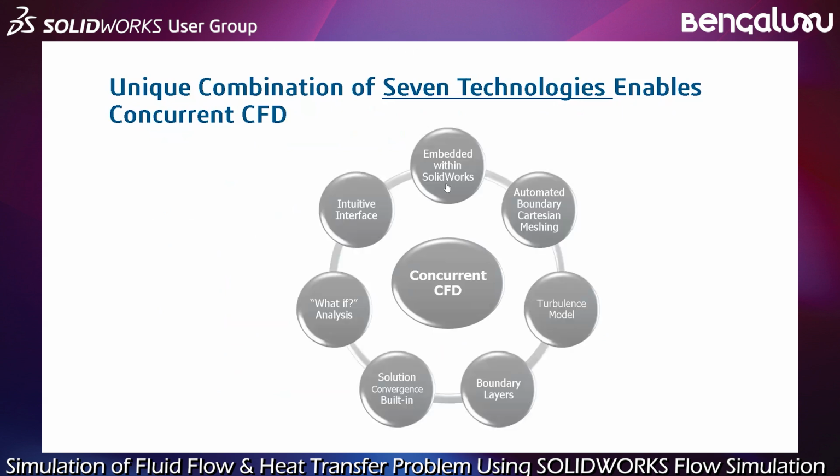The fact that it is embedded with SolidWorks, we'll see we have an automatic boundary Cartesian mesh. The mesh is very easy to set. It automatically takes into account the turbulence model so that the user doesn't need to select anything. Boundary layers are automatically calculated. As well, there are some tools to get good convergence, and you may deal with what-if analysis, and you'll see it's a very intuitive interface. This combination makes the tool concurrent engineering for CFD.